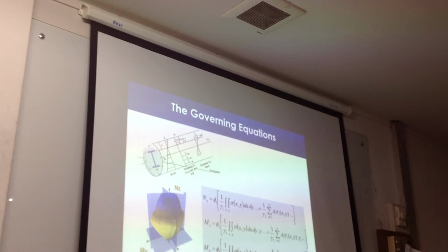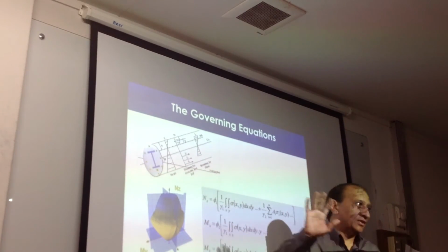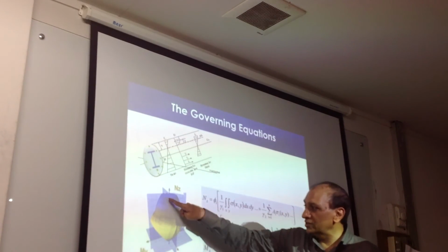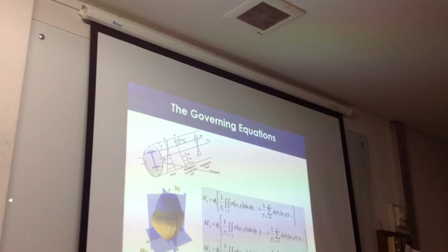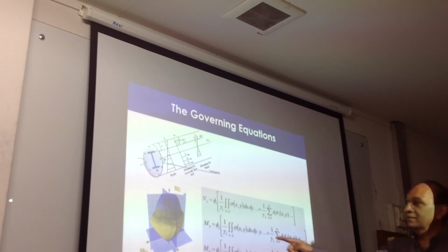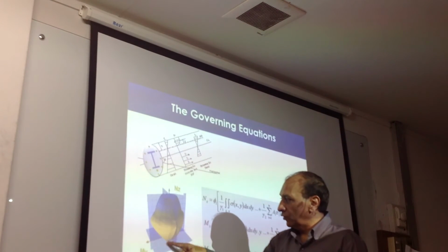Then we divide the work between two people: people who work on the computation side and the engineers who use the computations. Okay? So the computation side will say, okay, I understand your problem. What I'm going to do is generate this surface for you, for all possible combinations of the neutral axis rotation, and then this becomes the failure surface for your cross section.